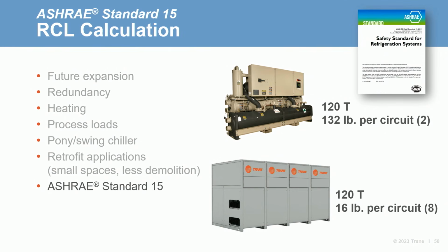If this happens in the machinery room, mechanical ventilation must be activated to disperse the charge. With less refrigerant released, assuming the same type of refrigerant is in each chiller, less ventilation is required for dispersal. Therefore, fans and ductwork may be smaller for a modular chiller when compared against a packaged chiller of the same net capacity for the same sized machinery room. To learn more about ASHRAE Standard 15, refer to the 2021 Engineers Newsletter and Engineers Newsletter Live programs or the standard itself, all referenced in the bibliography for this program.